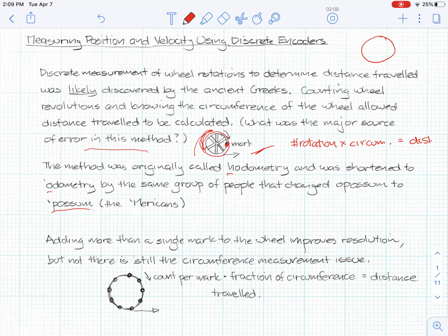Tire inflation changes with temperature, the pressure, all that kind of stuff. It's just very difficult to know. Most places that do car measurements and stuff, here's my approximation to a car, you'll see them doing tests on test tracks with that little wheel tied on the back. The reason that's there is because it's independent of the pneumatic wheels on the car, and so by putting a hard wheel on this, you can get relatively accurate measurements where the diameter of that doesn't change very much.